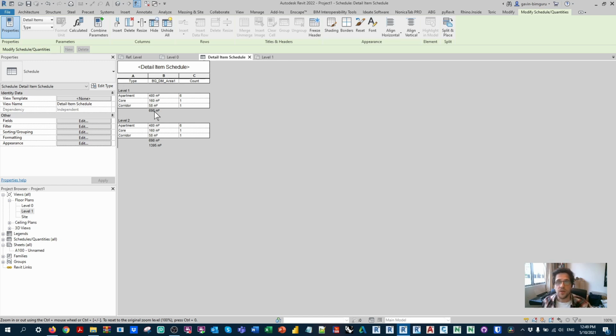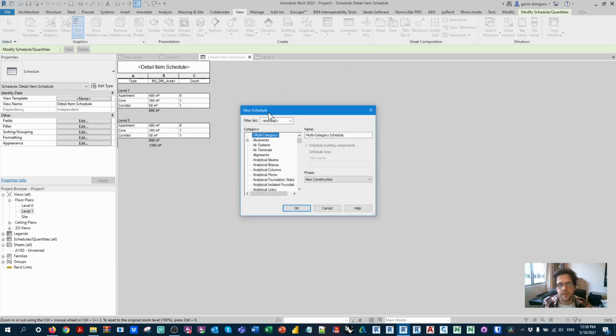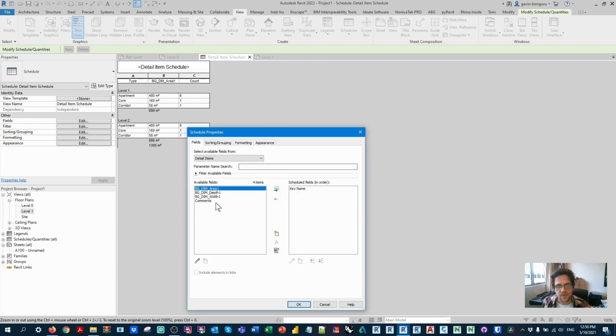We could go one step further on top of that by applying rates to determine the efficiency of GFA, or gross floor area, that these generate. So in this case, I'm going to make a schedule under detail items, and I'm going to make it a key schedule. And I'm going to say in this case, this is the area efficiency. And that's going to be the name of the key value that we're using to determine other values. So in this case, I'm going to firstly probably need another parameter for these, which is going to be their GFA area. But all we're really going to be doing here is controlling one parameter using the key name.